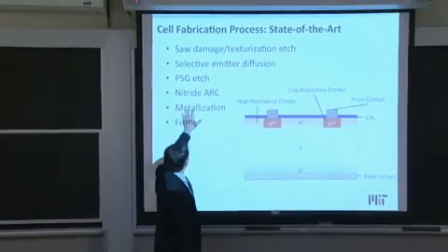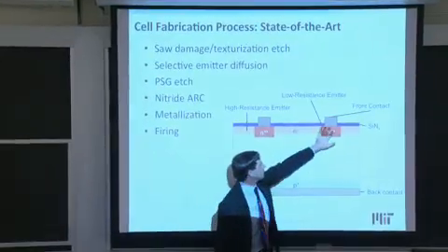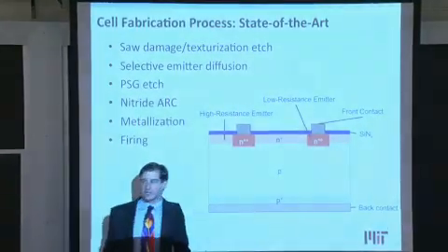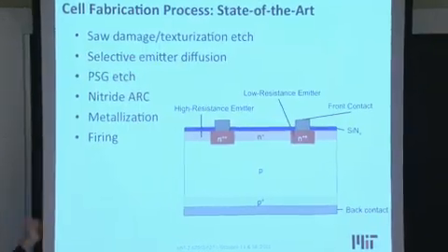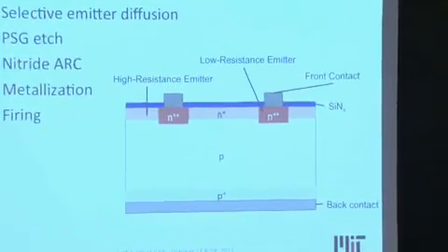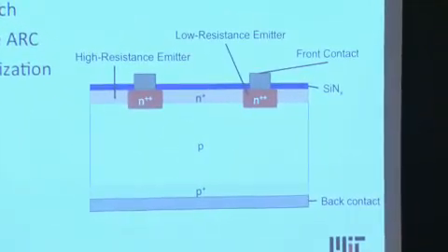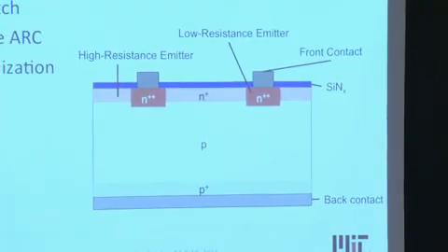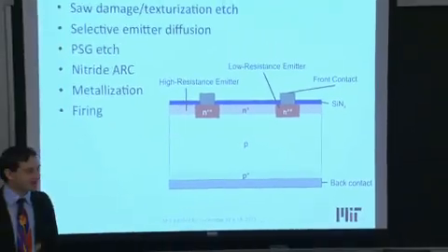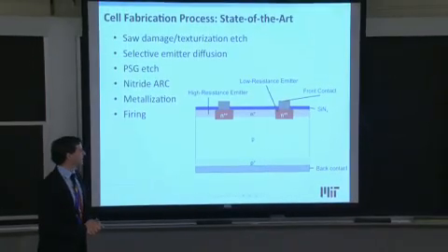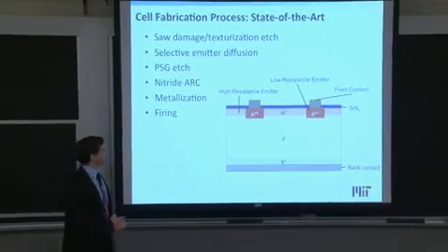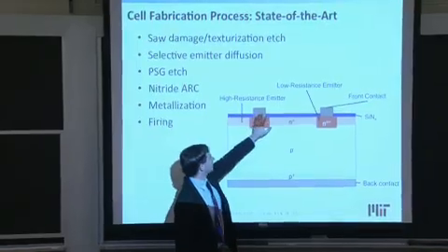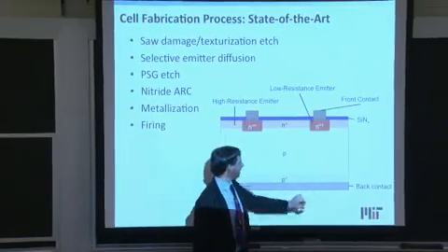And finally, the metallization is deposited on the sample and fired. Now, the metallization, how is it deposited? We'll see in a few slides what the screen printing process looks like, and then we'll actually do it ourselves. You'll press the button on the tool and deposit your metal on your cell. But the metallization is typically deposited onto the devices on the front side and on the back.